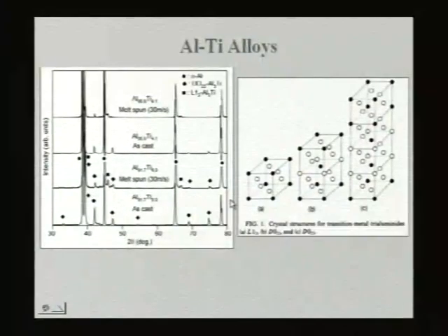So we also go to other type of nanocomposites where there are no amorphous phases, no quasicrystals, just simple aluminum plus nano intermetallics. This is one such example. We started talking about it in the last class, aluminum titanium alloys. I told you the aluminum titanium alloys have one important aluminide which is Al3Ti. The advantage of Al3Ti when compared to all other aluminides is because it has large amount of aluminum. It has 75% aluminum,